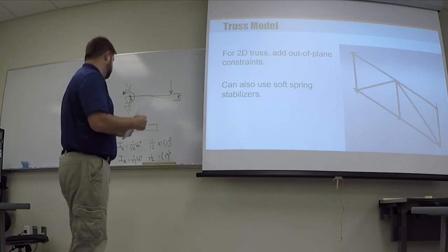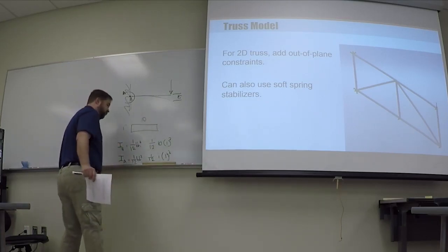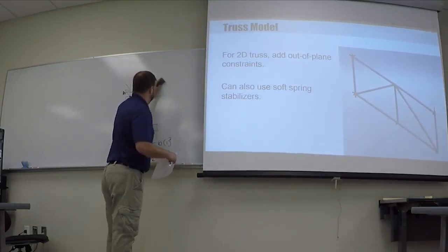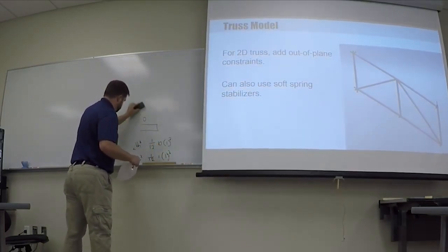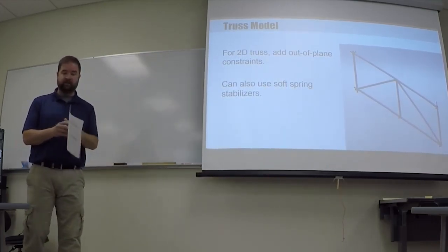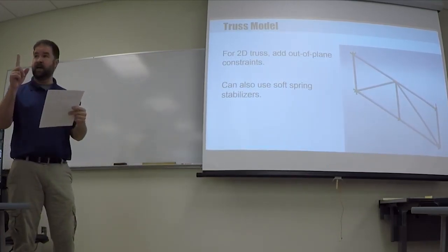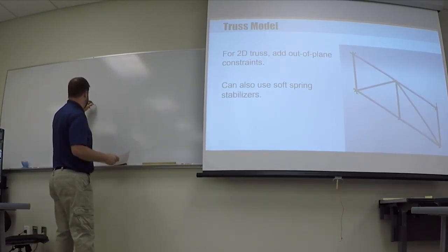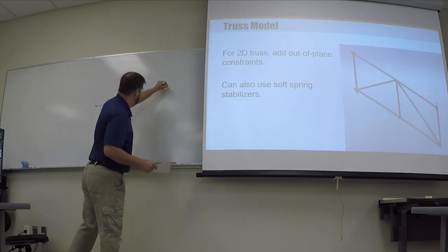So in SolidWorks, you're going to create a sketch. If I am doing my single beam element for my tapered beam, you're going to create a sketch that has a line that is 50 inches long.